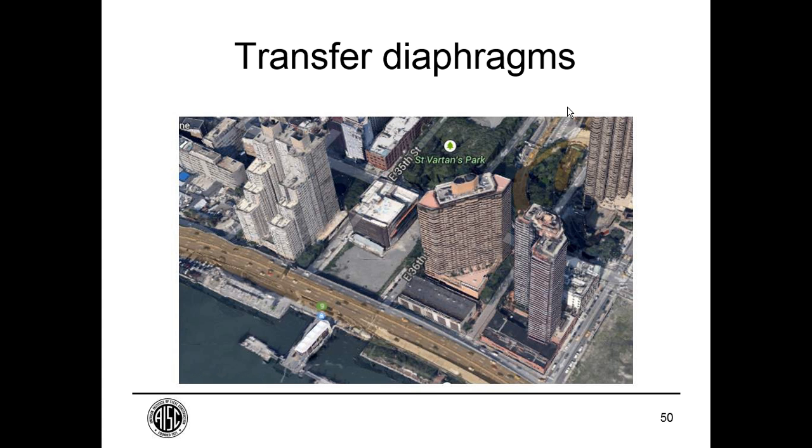And so when you look at this waterfront in New York, where for a variety of reasons, setbacks have been a very important part of the design of buildings in New York. Wherever you have these setbacks, or where you have a podium structure, there is a tendency for lateral loads to redistribute based on changes of where the mass is, and also changes in location and number of frames. And so especially for taller buildings, there's a lot of redistribution of forces from one frame to another, especially when there's some sort of geometrical change like this.